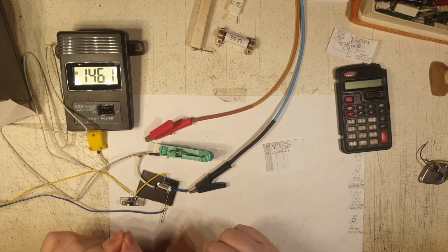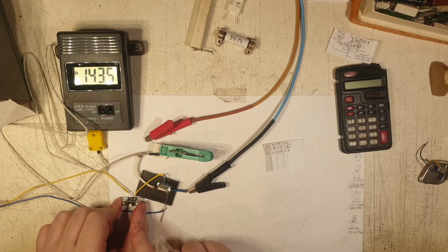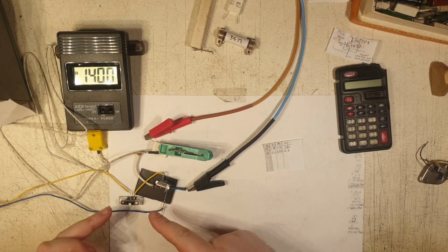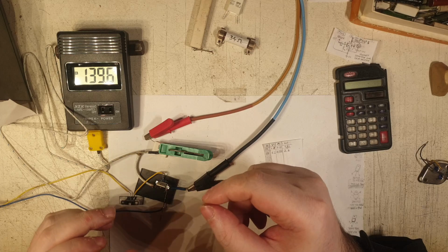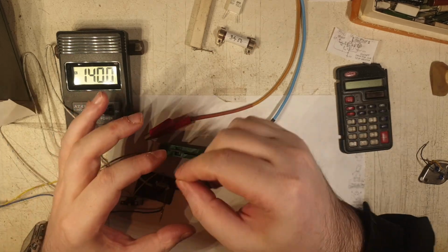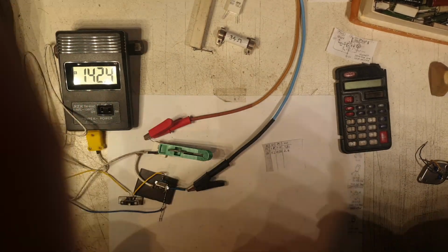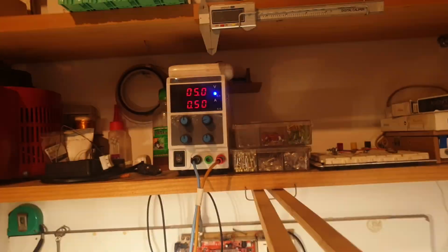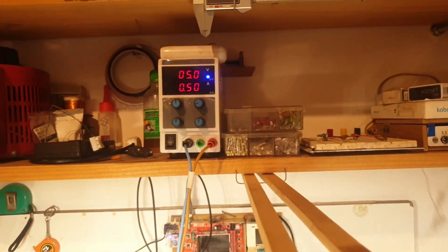Do you see how I'm moving it like that? If I was doing it one time like this, the MOSFET was already burned from only one test of switching like that. And voila, it is still the same voltage, the same amperage there. So that's my guide, that is guiding me if the MOSFET is dead or not.